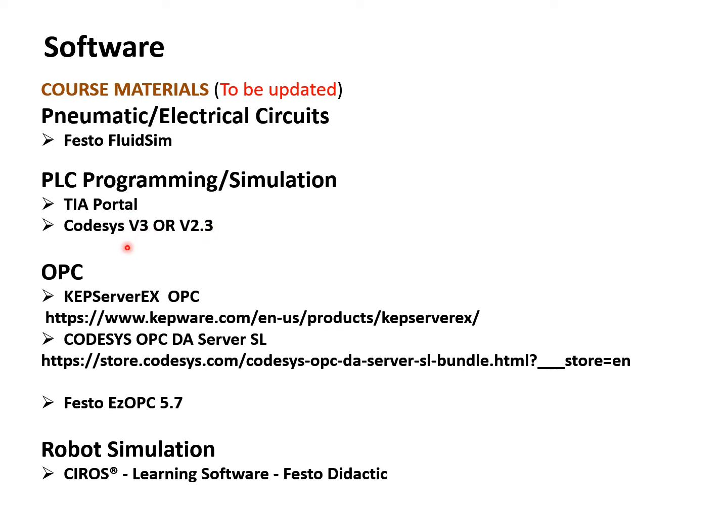we have different options for the OPC. OPC is a connection between this PLC programming and any simulation environment. Even a connection between this PLC and Factory I/O. Of course, we don't have a license for Factory I/O, but anyway, you could use OPC to connect that.